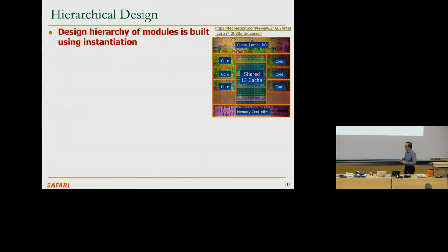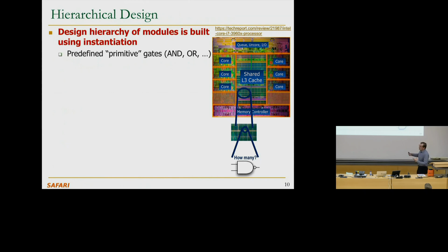Okay, so we're going to look at Verilog. Basically, the design is going to be very much similar to software engineering. We want designs that are hierarchical, right? You don't want designs that are a mess, that do not have modules. So we're going to build hierarchy into our design because the design is complex. If you look over here, it's hierarchical also. If you have, let's say, a shared cache component, then the cache component consists of smaller arrays, and arrays consist of gates in the end. So basically, we're going to instantiate small stuff and then build up.